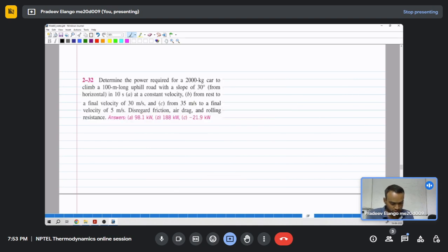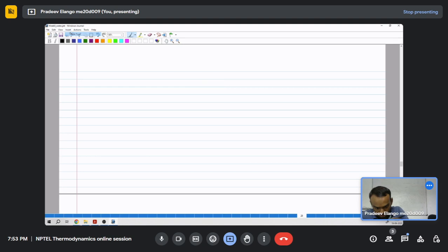So writing the steady flow energy equation, we will have the change in internal energy of the control volume. This should not be confused with the change in internal energy of the air coming in and going out. Change in internal energy of the control volume is heat given in minus work extracted out. Generally we assume positive heat transfer means heat is transferred to the system, and positive work is work done by the system on the surroundings.